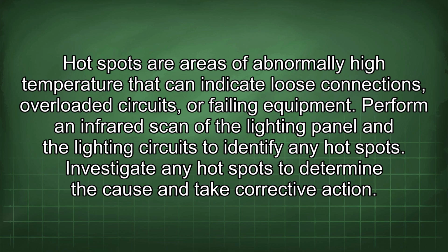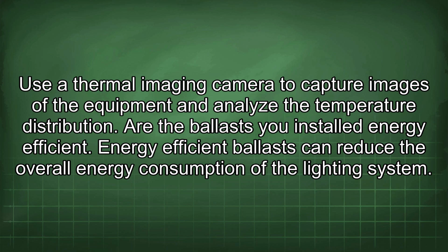Perform an infrared scan of the lighting panel and the lighting circuits to identify any hot spots. Investigate any hot spots to determine the cause and take corrective action. Use a thermal imaging camera to capture images of the equipment and analyze the temperature distribution.